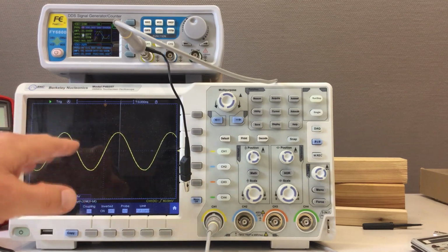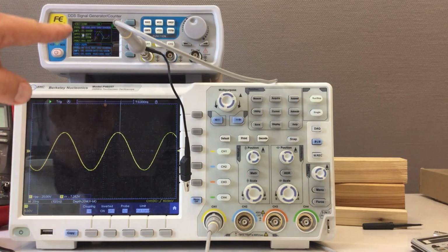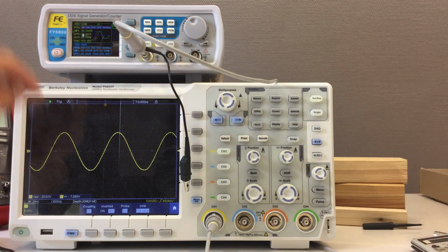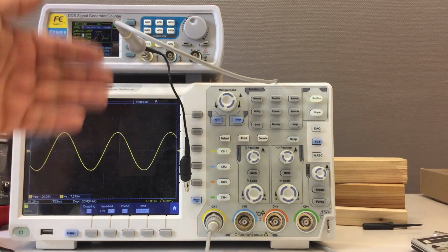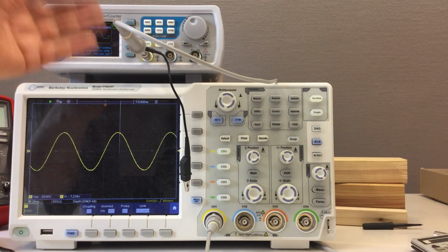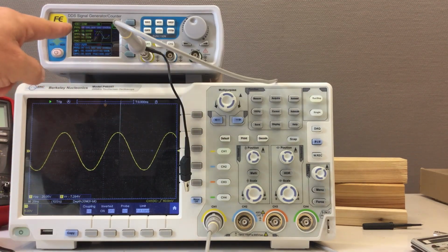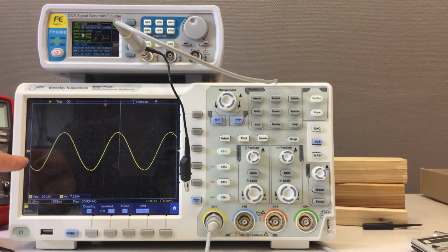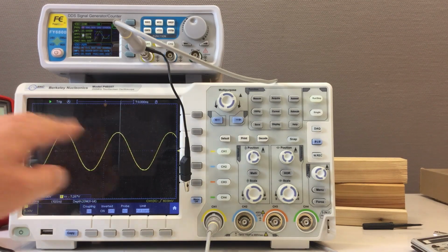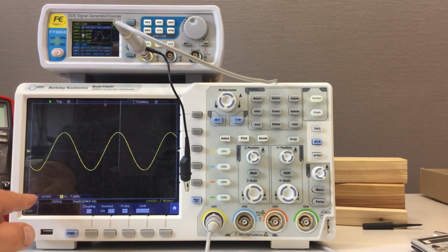In this case, we can actually use a set voltage of 20 volts peak to peak because we're not drawing any significant current out of the unit. And you see, I have 20 volts here, and at 9 megahertz, I get a nice sine wave with a peak to peak voltage of exactly 20 volts peak to peak.